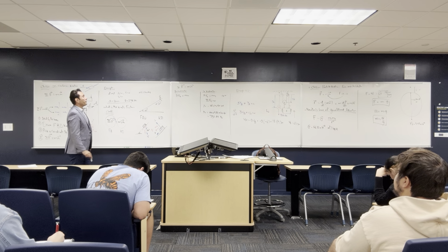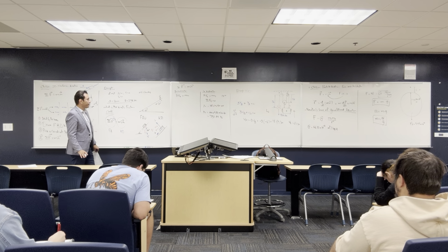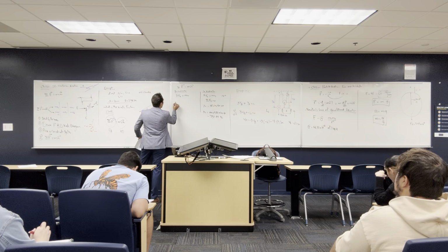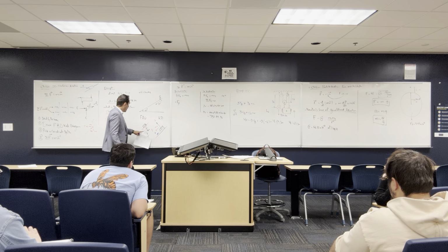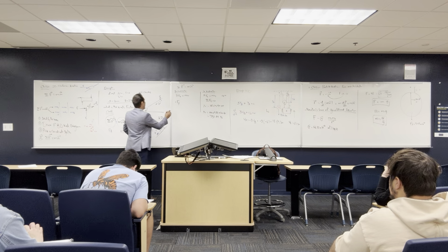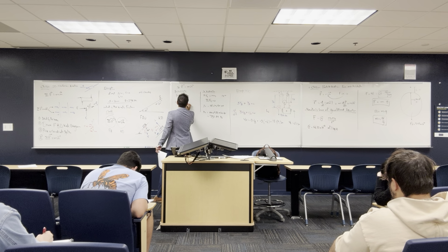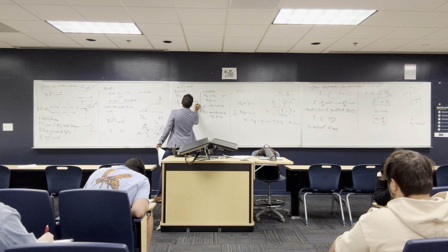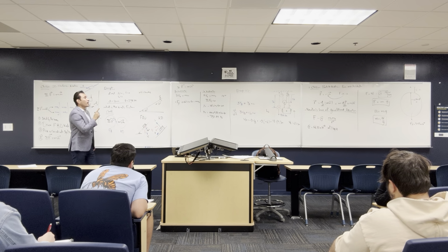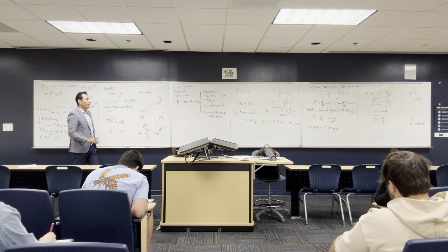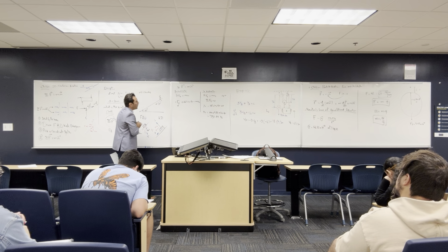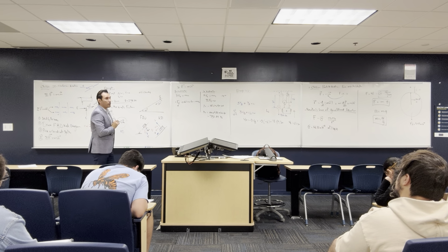Okay, let's take the x direction. What forces are in the x direction? The friction. Is the friction positive or negative? Negative, so I have negative F friction. What are the other forces? The sine of the weight. So I have it positive, so plus W sine 40, and this is going to be equal to max. Why? Because I have an acceleration going down. The thing is, I don't know what the ax value is, okay? And the friction value is, do you guys know what the friction value is?